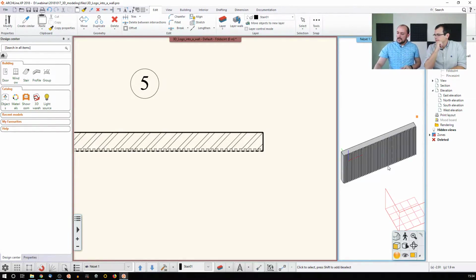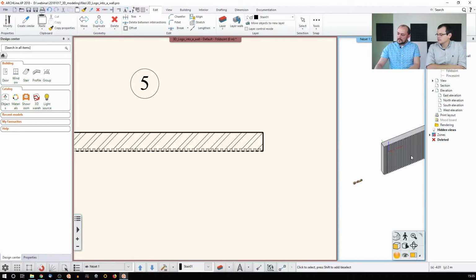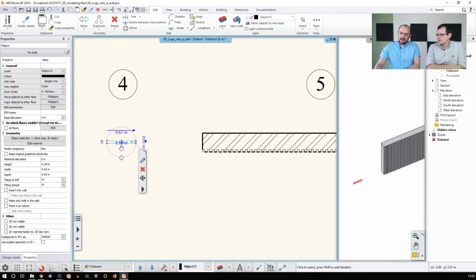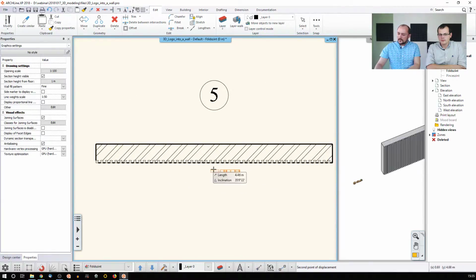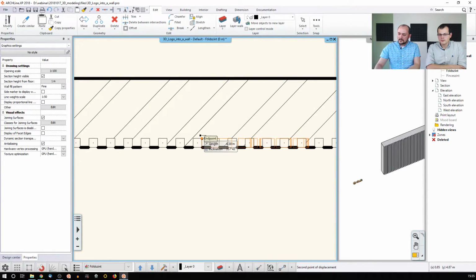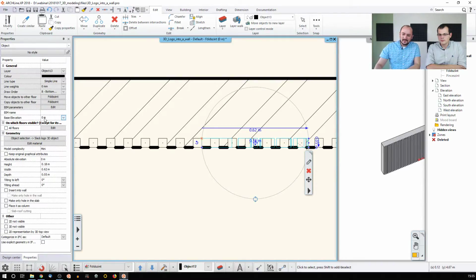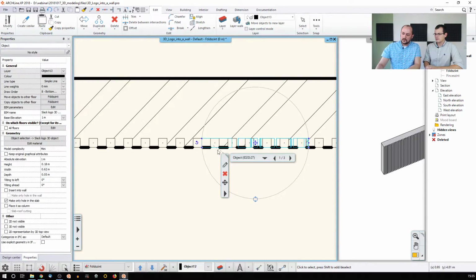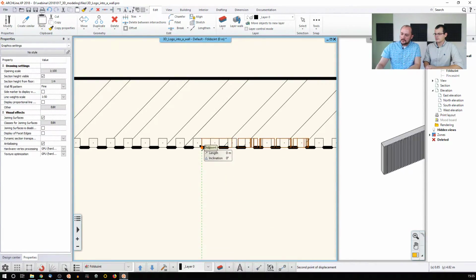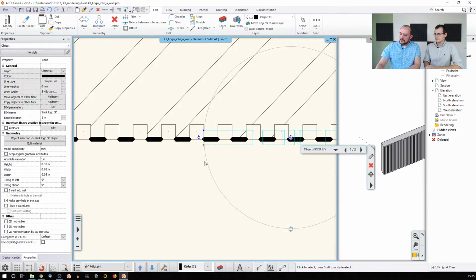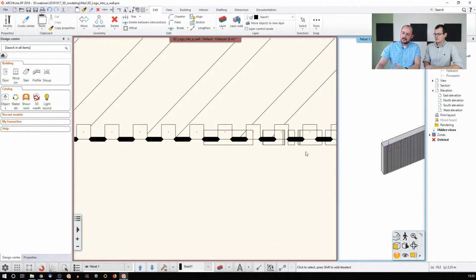So what's the next step? To insert this into this design, all I need to do is to move it with a specific point like this, and I think I just paste it over here, elevate it to the proper space. I mean, this should be a meter or so. And then what I need to do is to find the same option. It's make only hole in the slab, and this is how it goes. This actually is removing itself from the wall. I think perhaps I need to move it a little bit downside, so I can get this 3D shape.